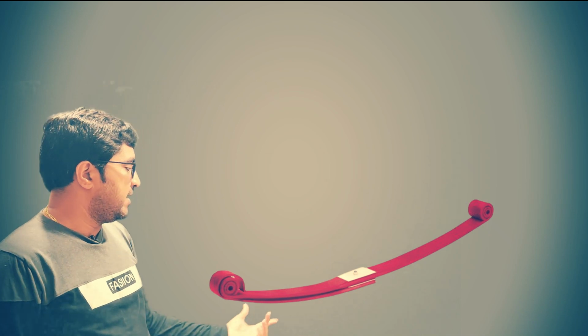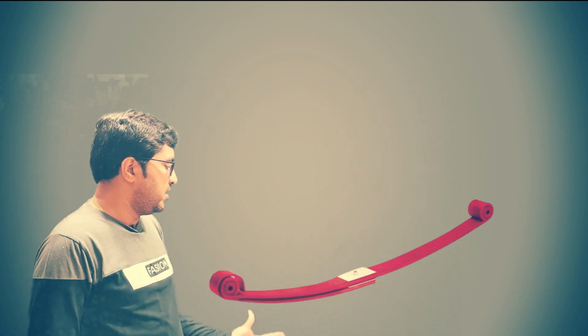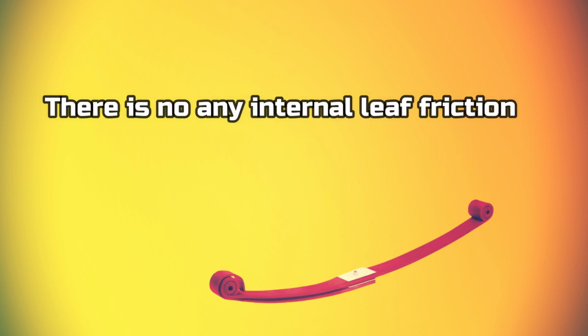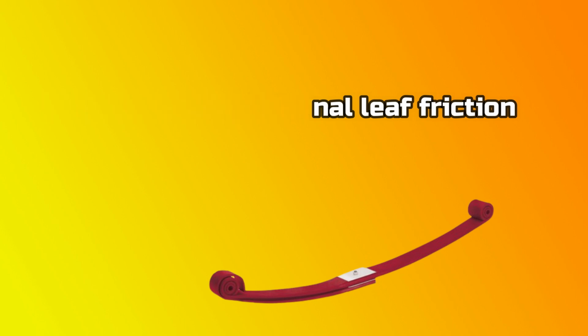And the next one is the taper leaf spring. It is also called the taper light leaf spring. Here we are using only one leaf. We use high grade steel material for manufacturing the taper leaf spring. It is lightweight, nearly 60% of the corresponding conventional spring. There is no interleaf friction in the case of a single taper leaf spring, because here we are using only one leaf instead of a bundle of blades or leaves.